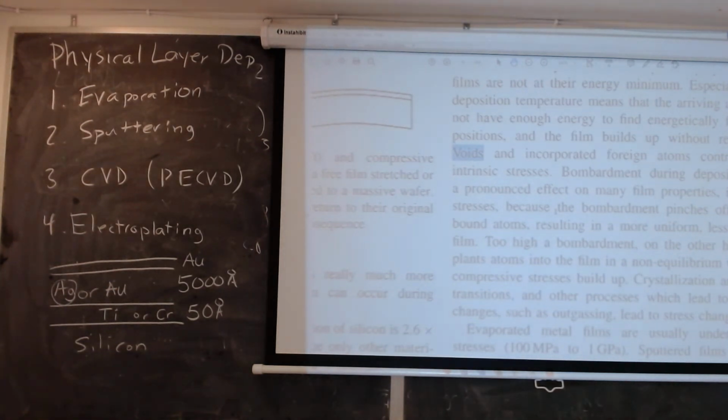And so what happens is that any material doesn't like having voids, and those voids will try to leave the film, basically either going up to the surface or to the sides even. And when those voids leave the film, the rest of the film has to move into place to fill the vacuum, so to speak, of what's left over.